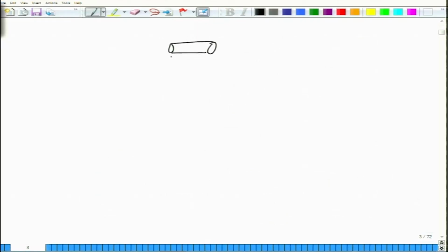While the forward pump drops down, is it possible for us to use a secondary pump in the backward direction, while the forward pump starts off very strong and then eventually falls off? What if we had another pump in the backward direction, which would start off strongly here and then go down as it goes, eventually creating an overall gain? It is possible for us to do so. This is called the co-propagating pump, and this of course is called the counter propagating pump.